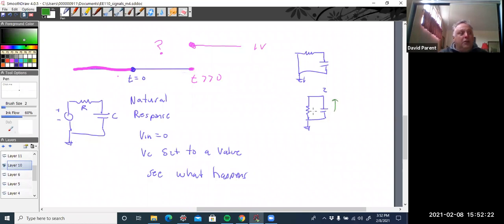Even though electrons are negatively charged, in circuit analysis, we always use the flow of positive charge. So that would be I1 coming out of the resistor, and then I would have I2 coming out of the capacitor, and I2 flowing through the resistor. So I have something entering the node, I1, equals something coming out of the node. That's nodal analysis.